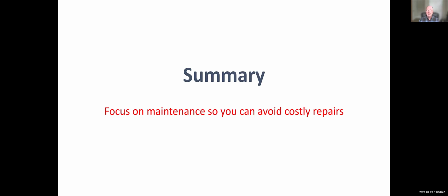Yeah. So you're doing the maintenance, but record what you're doing, where you're doing it, when you did it. And that record becomes helpful for both you as an owner, but if anybody's brought in to do a dam safety review or review your operations, you've got that record, and that becomes really valuable information for them too.